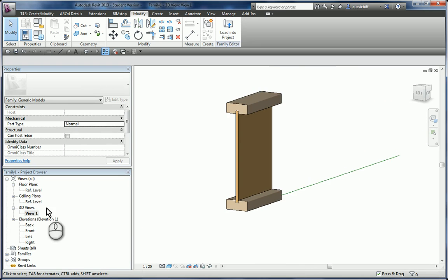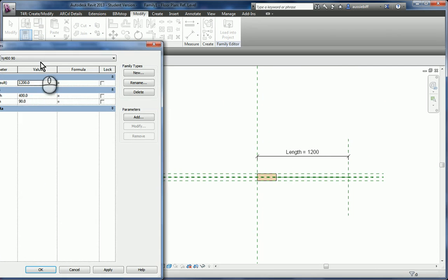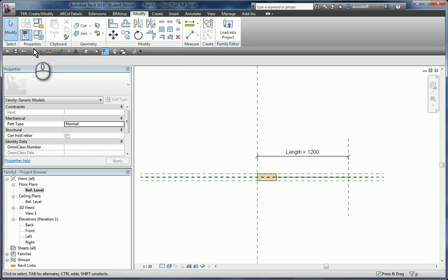Now there's one more thing we have to do. At the moment this isn't stretching down to that end, and it's not equaling our default length here. Very easy. Go for the align tool, come up here to this reference plane. We want to align both shape handles, the web and the other extrusion. So one, hang on, we'll do that again. Take that one to there.